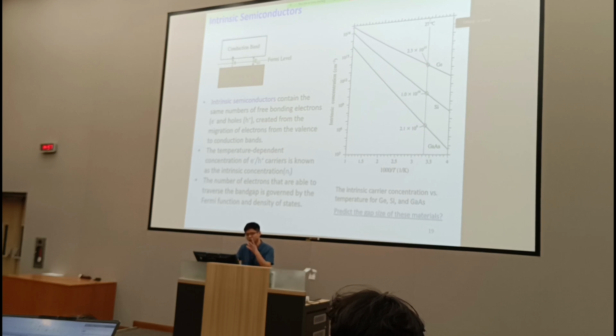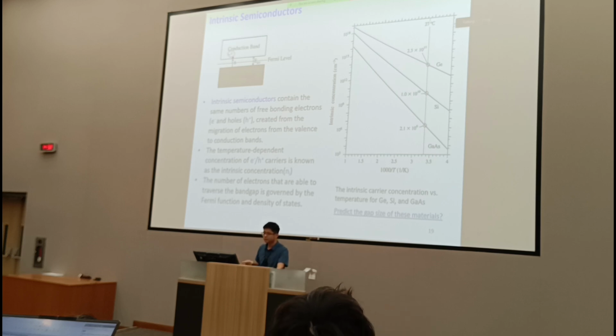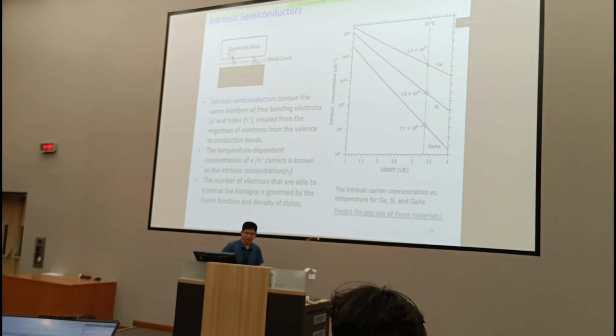The carrier is basically a charged particle, it can be electrons or holes, right? But it has to be mobile to be considered a carrier. To be mobile, you have to inject into the conduction band, right? So how to inject? You input energy. The electron doesn't jump into the conduction band without energy input. You input energy, you excite it.